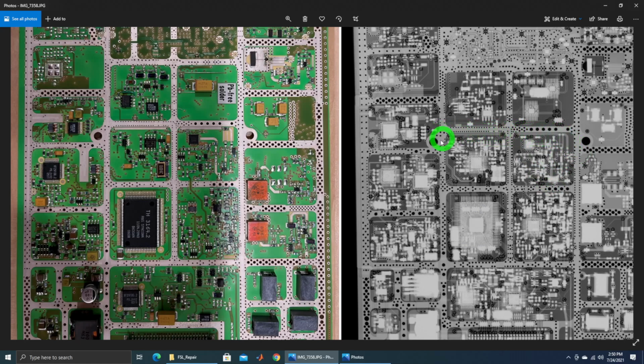And I looked at these components a little bit more carefully. There's actually a divider here, which is necessary. It was a little bit puzzling because I was not looking at this very carefully originally. And I looked at this component over here. This is our phase frequency detector. But this phase frequency detector was only rated up to about 1.5 gigahertz. So you couldn't connect the VCO directly to it, of course. So I was looking for that divider and eventually found it. That's over here. It's a divide by 4.